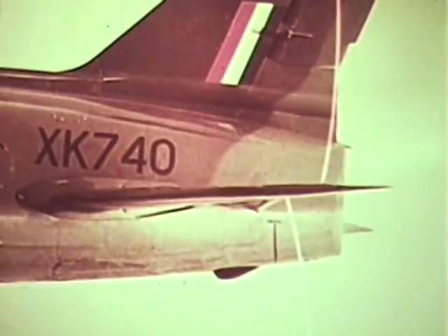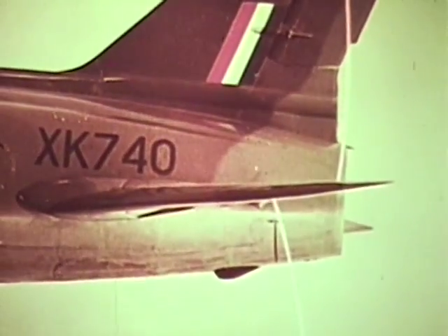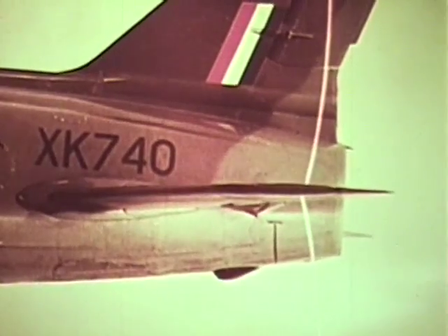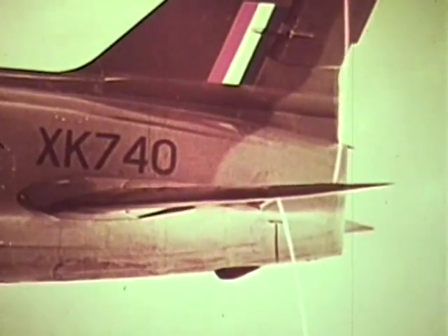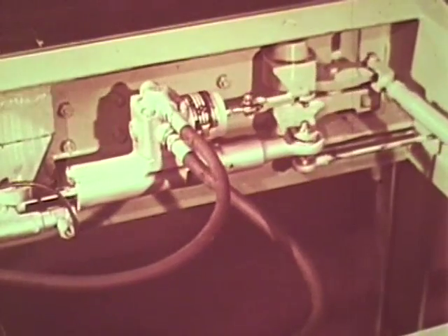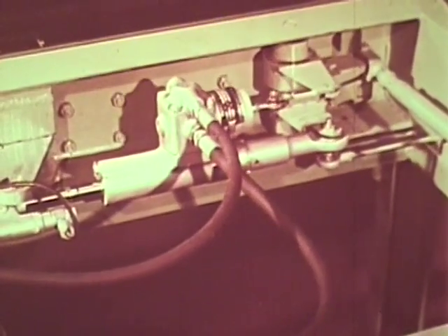Such moving tailplanes can give up and down trim control with smaller deflection than the elevators on fixed tailplanes. For proper control at transonic speeds, powered controls are almost essential to overcome the huge forces on the control surfaces.